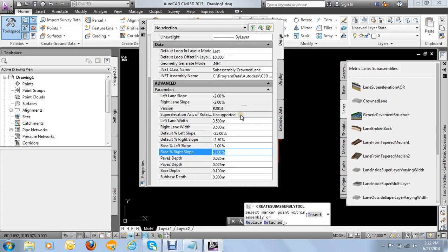Okay. For the normal roads, the sub base is normally like 0.2 or 0.25. Is it meters? Yes, it is meters. Okay, it's 0.2 for the sub base. And the base? 0.15. Yeah, I think this is it.